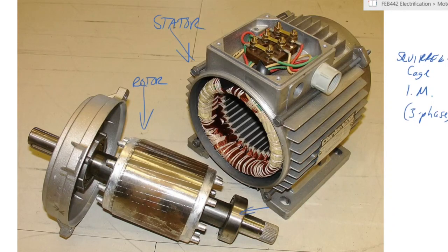If you look at this and inside there, let me draw it here. Inside there, you will notice that there are two bearings. Usually ball bearings or thrust bearings. Standard industrial bearings, very durable, usually greased for life. They don't need any maintenance. They don't need any lubrication. The reason why three-phase induction motors are the most commonly used and most widespread motors in the world is because of this construction. The only moving parts, the only things that experience friction within the motor are these two bearings.